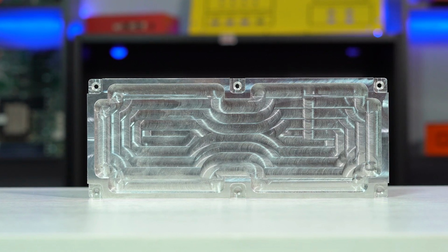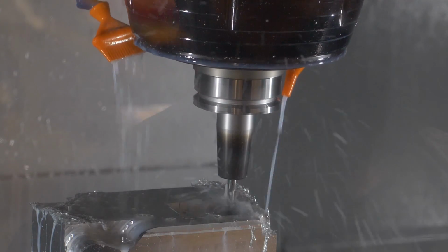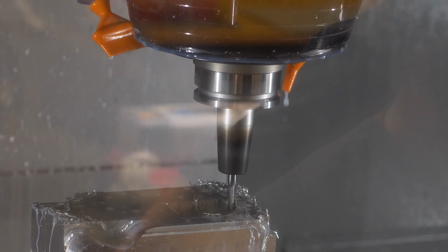The next design feature I want to talk about are pockets. Pocket is a term used to describe cavities of negative space within a part. Pockets can come in all shapes and sizes, rectangular, circular, and more. Pockets can be blind or cut all the way through a part. If a pocket has a side that's removed, they're considered open pockets. Pockets are generally roughed out and finished by end mills.